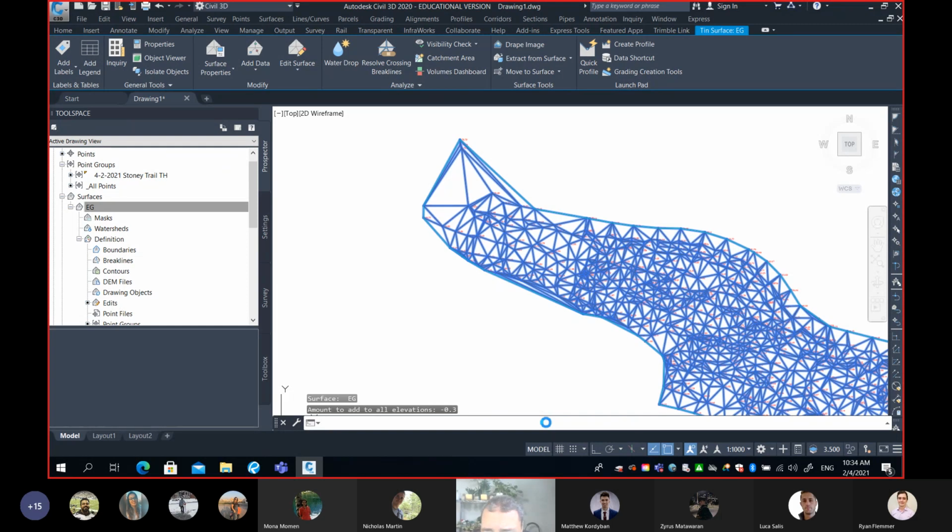If you want to raise, then you repeat the same command, but you add a positive number. Let's say you want to increase all the elevations by 10 centimeters, so you add 0.1. And I know some of you will say minus 0.3 makes sense. If you have topsoil, we can simply drop the elevation by 1 foot. So what are the cases where we need to raise the elevation by 0.1 meters? I know it's very hard to understand, or maybe very hard to get an example.